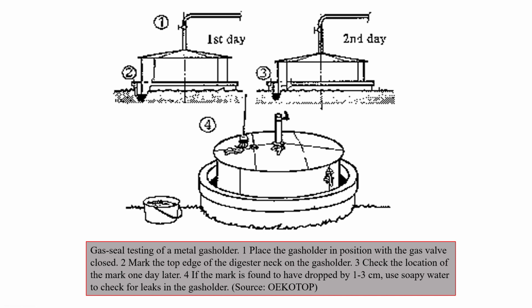Then only the gas holder will be moved down, right? That means there may be some leakages, and those leakages can be checked using soapy water. So that is about the gas seal test.